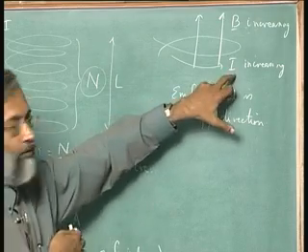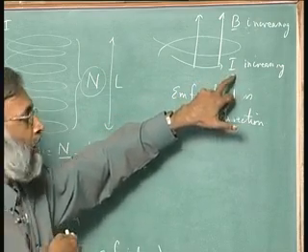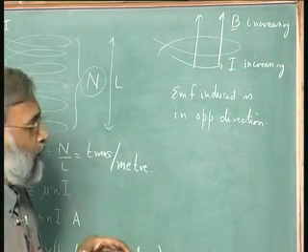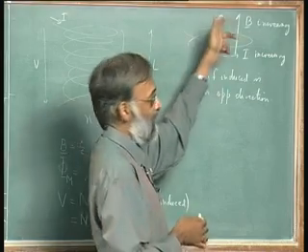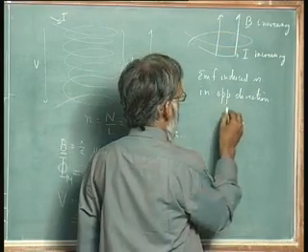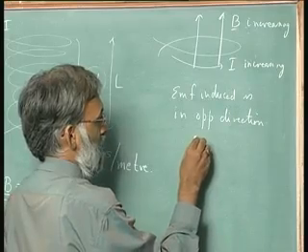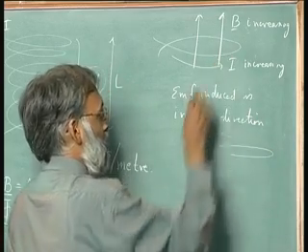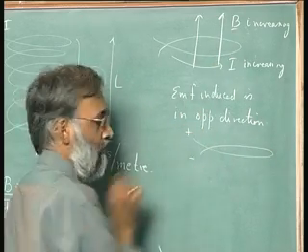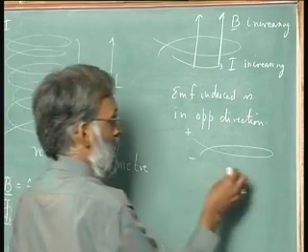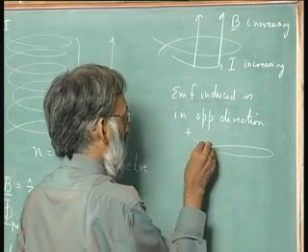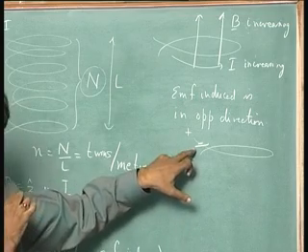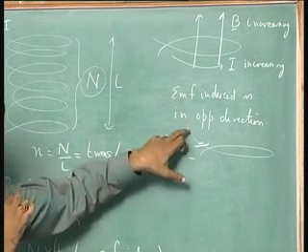So, if you still want to impose this increasing I, what you have to do is you have to apply an equal voltage in the direction of the current. So, it is as if for every turn there is a little battery, induced battery, that is trying to resist my applied battery.